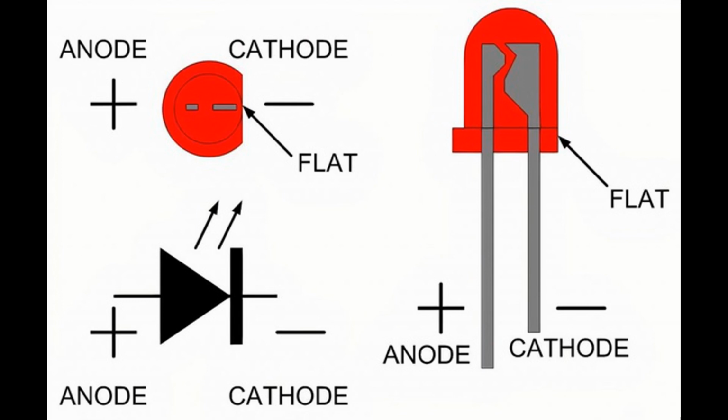Voltage-controlled voltage sources, VCVS, are electronic circuits that generate an output voltage that is controlled by an input voltage signal. These circuits are used in various applications where a variable voltage needs to be generated based on an external control voltage. VCVS is a fundamental building block in electronics and is used in a wide range of analog and mixed signal circuits. In a VCVS, the output voltage is proportional to the input control voltage, and this proportionality is defined by the circuit's gain or transfer function.